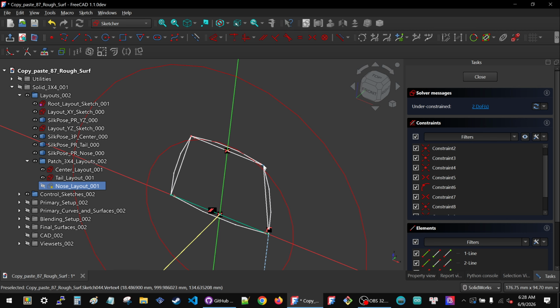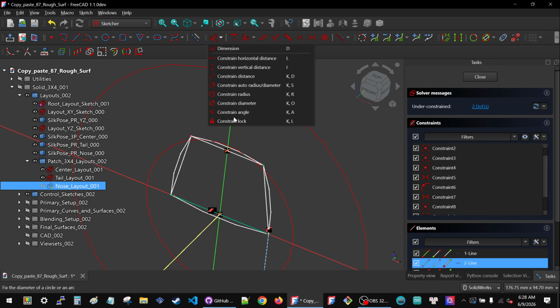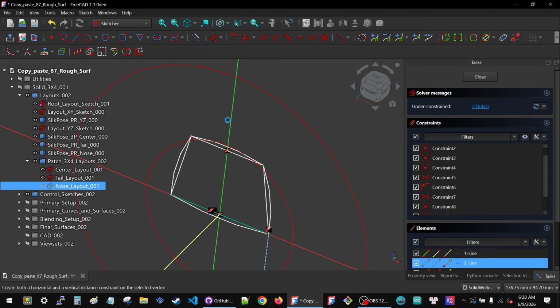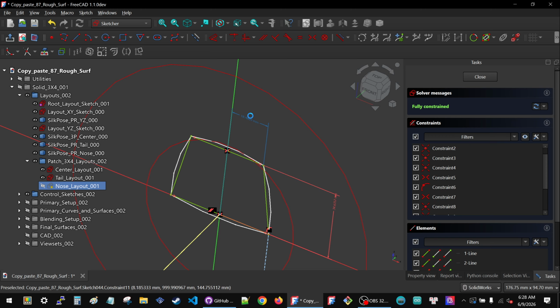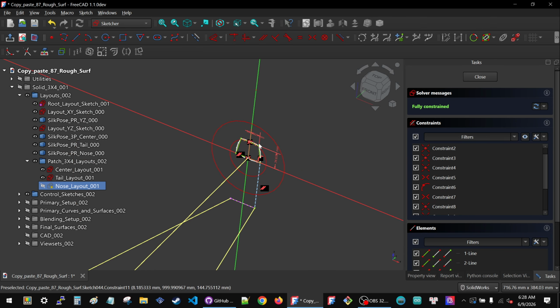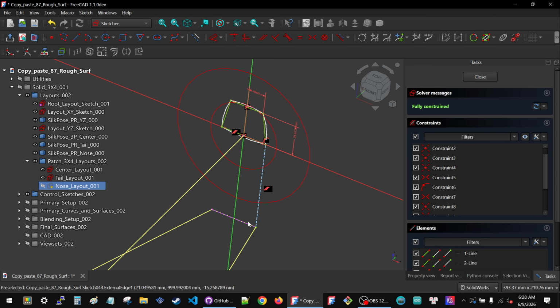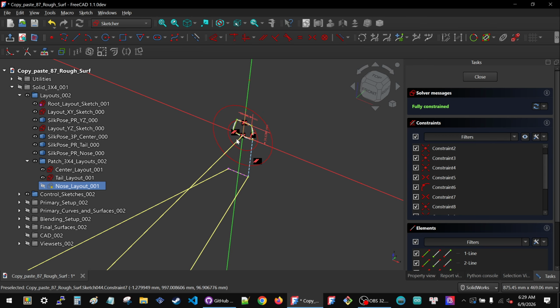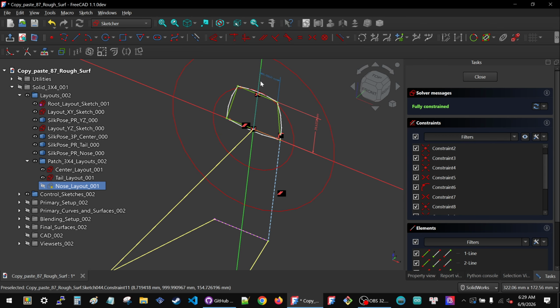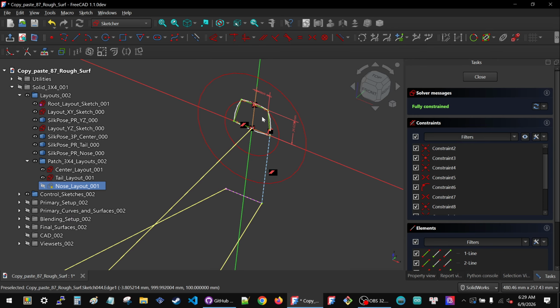And now I'm going to put a dimension back on here. And I'm going to use my constraint lock. And notice that that's it. I'm completely constrained now. This sketch only contains 2 dimensions. The size of the layout in this dimension comes from my overall XY layout. The position of the bottom line comes from the YZ layout. All I can decide is the respective size of the rail and the top surface. And the rest is defined by symmetry.